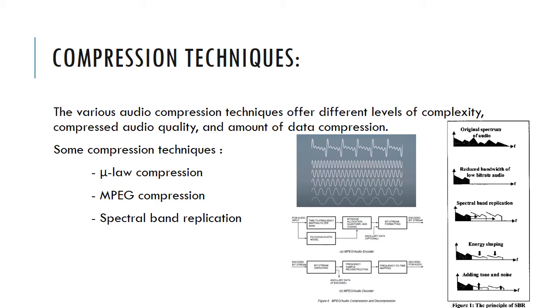The mu-law quantization, used in phone systems, uses 8 bits of data to provide the dynamic range that normally requires 12 bits of PCM data. It is a low complexity, low compression technique and provides medium audio quality. The process of converting a computer file to mu-law is a form of compression, since the amount of data that is needed per sample is reduced and the dynamic range of the sample is increased. The result is much less data with more information.